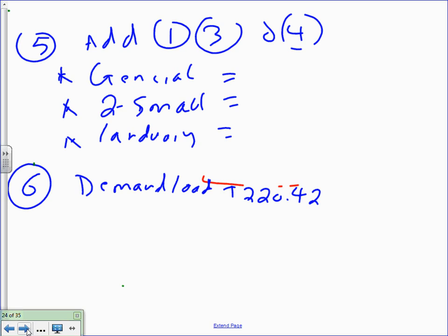Okay, now this is when we add them all up. I want you guys to give me the general lighting. What was the size that we came up with? I know this is 30K, this is 15K, and the first one was 123K. Add them up. So this is 50, 60, 168. 168 kVA. Okay, cool. That's a piece of cake.